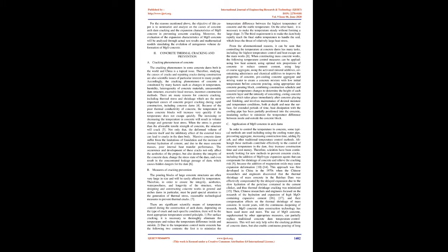There are many reasons for concrete cracking, including thermal stress and shrinkage, which are the most important causes of concrete project cracking during rapid construction, including concrete dams. Because of the poor thermal conductivity of concrete, the temperature in mass concrete blocks will increase very quickly if the temperature does not escape quickly. Increasing or decreasing the temperature in concrete will result in volume change and generate heat stress. When the stress is greater than the allowable tensile strength of concrete, the structure will crack.